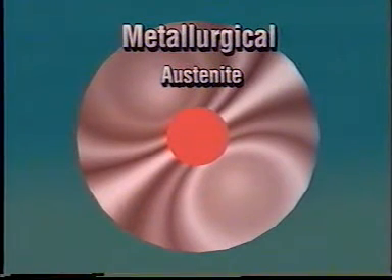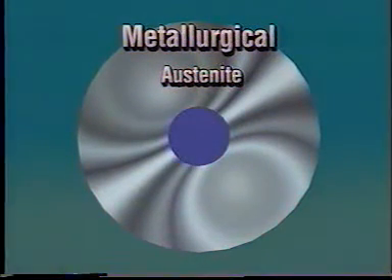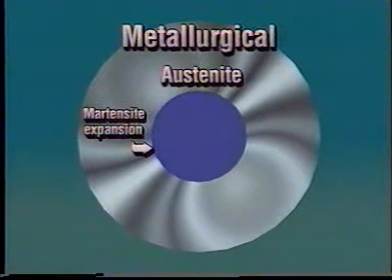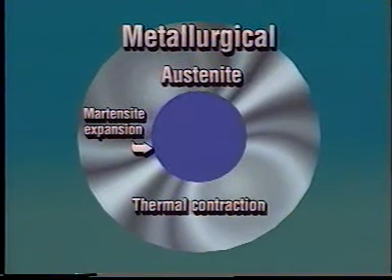Residual stresses by metallurgical factors occur primarily in the martensitic transformation of steel. When steel transforms from austenite to martensite during cooling, the martensite expands about 3 to 4% by volume, depending on the carbon and alloy contents. This expansion causes compressive residual stresses in the transformed region of the part, if there are other regions that did not transform or transformed earlier, depending upon the hardenability of the steel. The principle of metallurgical residual stresses in steel is this: the metal that hardens last is in residual compression.